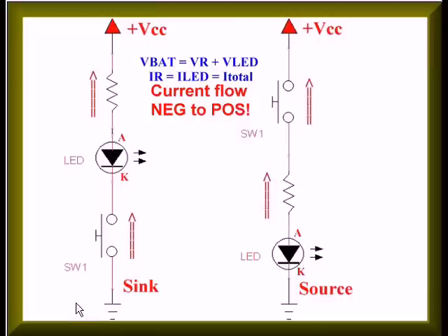In this lecture, I'm going to use negative grounds only, and it's important to note how the switches connect in the series circuit. A series circuit is where the current flows through all the devices, and it will be the same current. So the same current through the switch when pressed is the same current through the LED, through the resistor, back to VCC. Same thing over here. The order of the components doesn't really matter with a push button switch. It matters a great deal with a solid state switch. You can't just put them anywhere in the line.